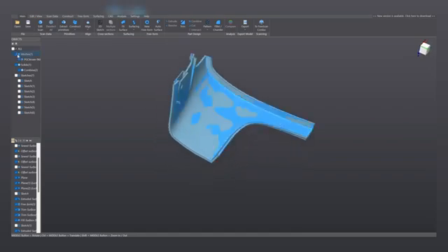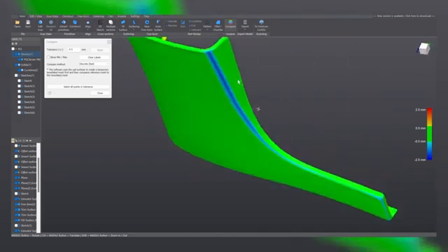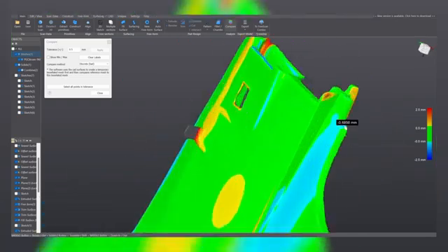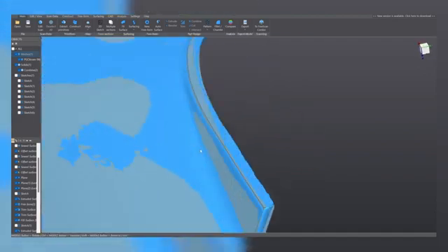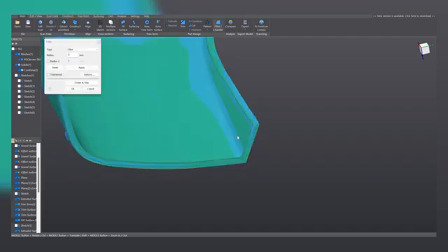And before completing the process, if we take a look at the comparison, we observe some errors here, right here, over there too, here as well. Well, the fillets are missing, and this is the last operation we would carry out. So to do it, just select the surface and click on fillet, and now you should be able to select the edge.